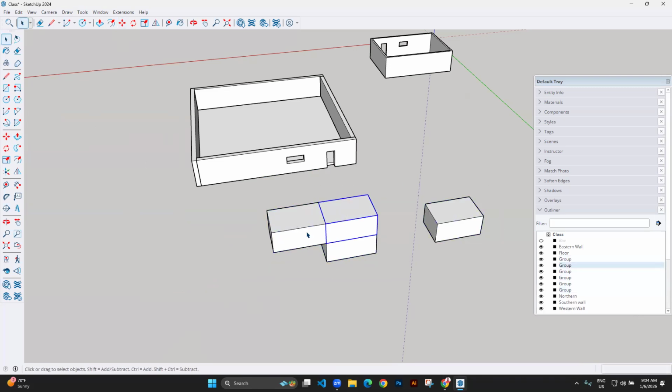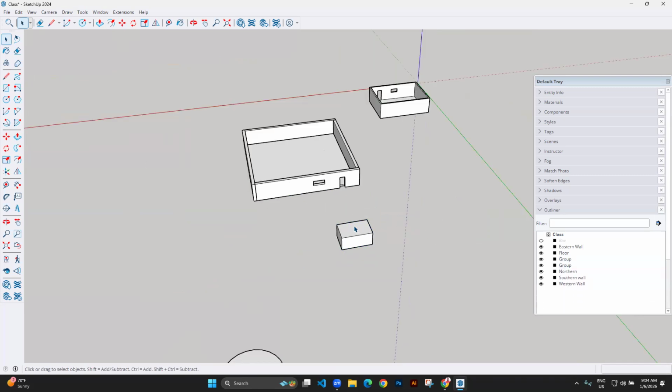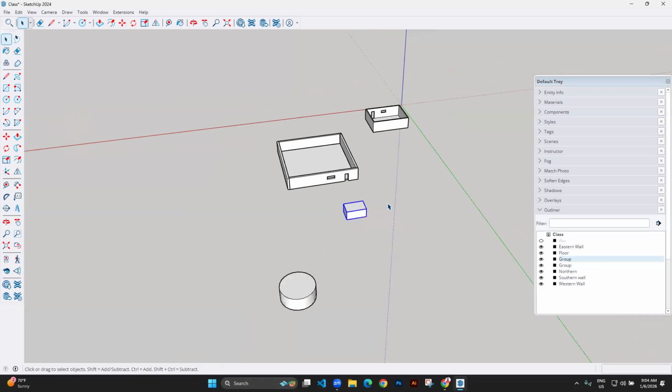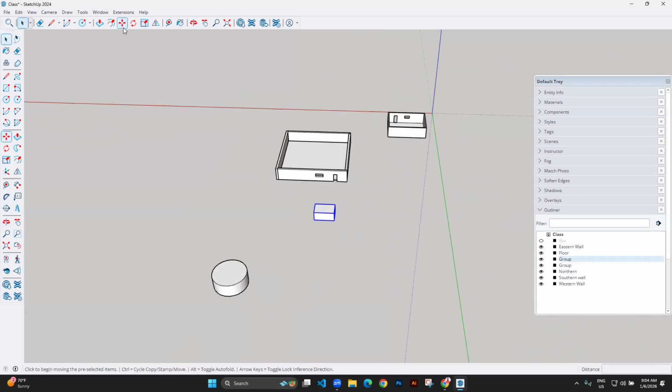Then lastly, in copying and moving, you can do multiple duplicates. How? Say I'm copying. Press Control. That is the distance. Then you're like, I need 3 more copies of that. After completing the copy, you just press X to mean times, then you type in 3 to mean 3 copies. So instead of 1 copy, it will create 3 copies.